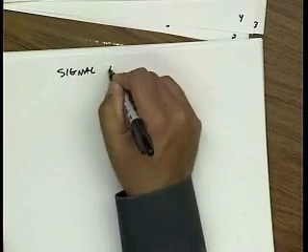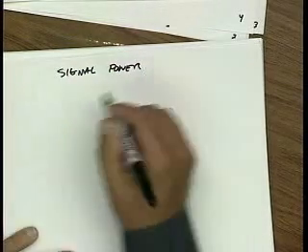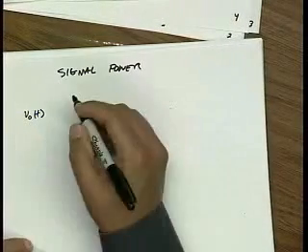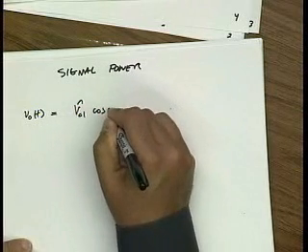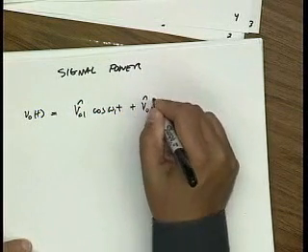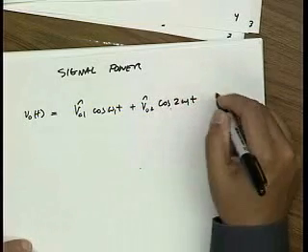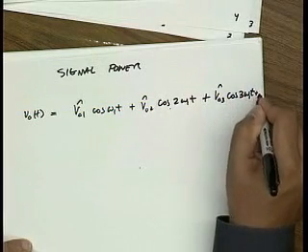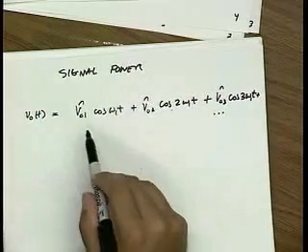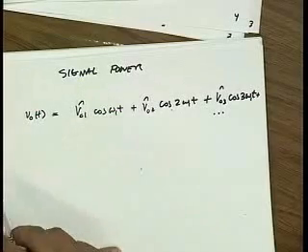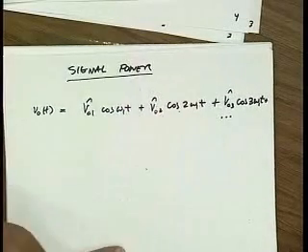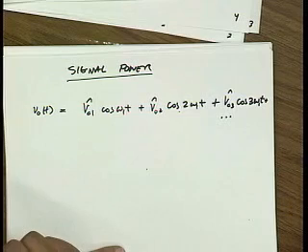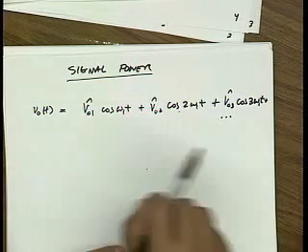So let's start out with the signal power. So our output signal is basically a Fourier series. We put in a sinusoidal input, and at the output we have basically some signal at the same frequency plus all the harmonics. Now remember, a linear time invariant system cannot generate output frequencies that are not in the input frequency. So you need a nonlinear system to make this happen.